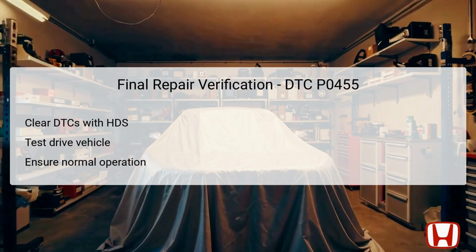Once any necessary repairs or replacements have been made, it is crucial to verify that the repairs have been successful. Begin this verification process by using the HDS to clear the diagnostic trouble codes, DTCs, from the PCM. This action resets the system and allows for a fresh diagnostic session.